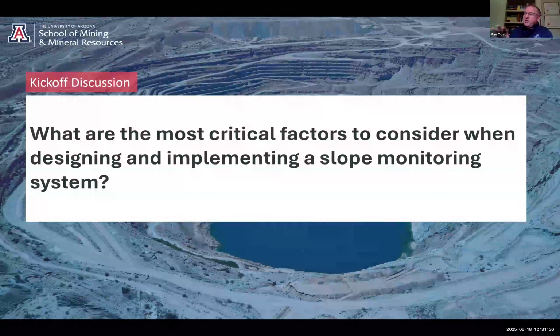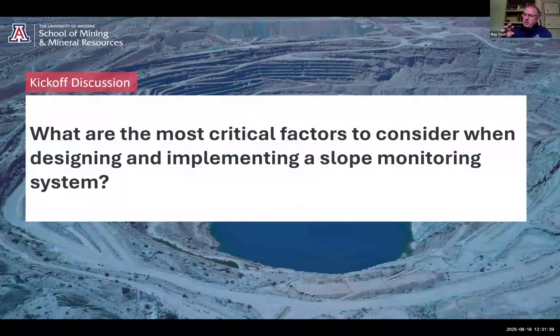The other thing I see, I'm going to pick on some of the technology folks a little bit. I love radars and I love what they can do, but they're also resource intensive. You have to think about this balance of resources that you have to babysit all these systems, to take care of them. Sometimes if you're out there looking at, I'm going to put some prisms in there, put an RTS up, and that works pretty well, versus the resources that go into a radar.